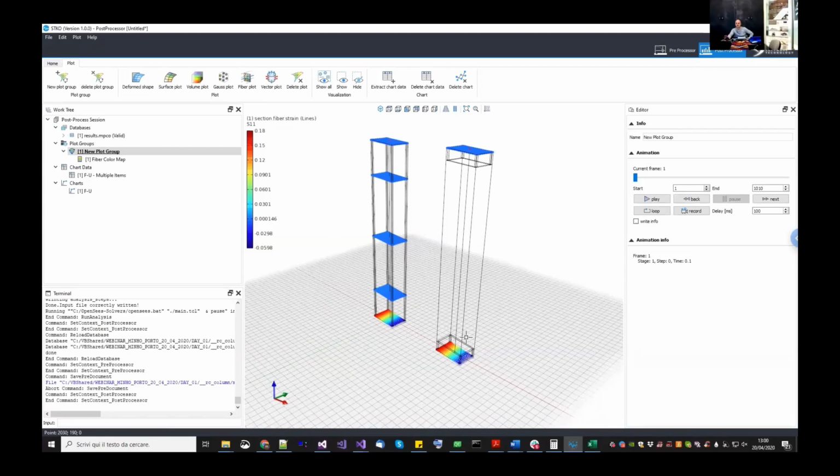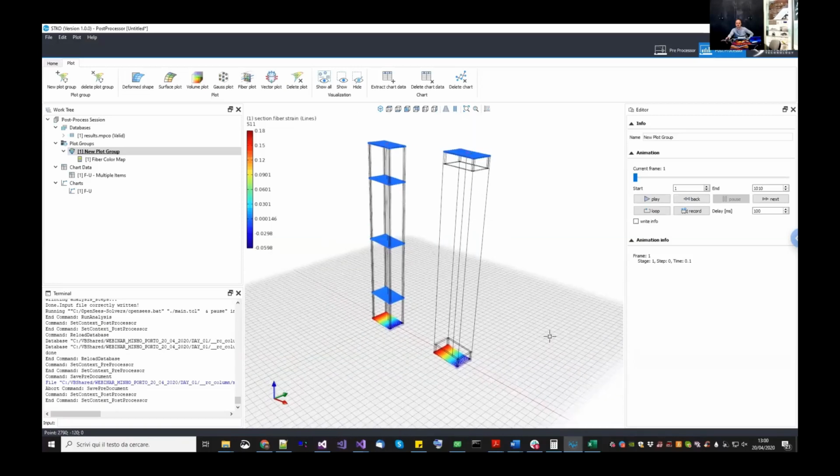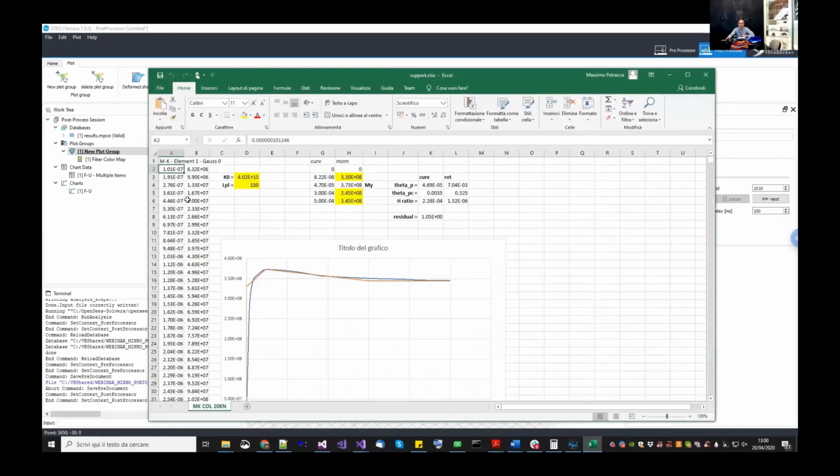The disadvantage of that approach is that you don't have the coupling between the axial force and the bending moment. The advantage is that it is much faster, of course. And if you don't have information about the fiber cross-section, you can directly input the moment curvature. Now, in this example, if you remember before, we extracted the moment curvature at this point, and we copy-pasted it here. So in this example, I will show you how to use the typical model that people use in OpenSees for lump plasticity in terms of moment rotation, which is the modified Ibarra-Medina-Krawinkler model.